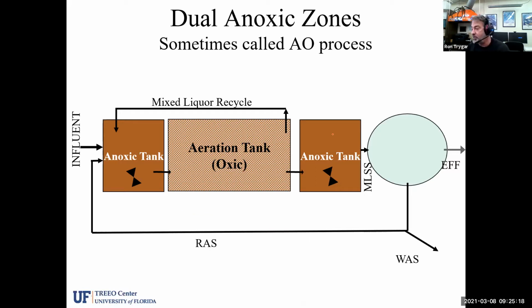And you notice that we have a post-anoxic tank. You may have to feed some carbon right here, because we can't always rely on the endogenous carbon. So we may have an external carbon source being added. Remember, we had different forms of that. And then the nitrate number may be much, much lower than before. We might have a very substantial reduction of the total nitrogen into nitrogen gas, and maybe get our total nitrogen numbers down to close to 3 or even less than 3 in this case.